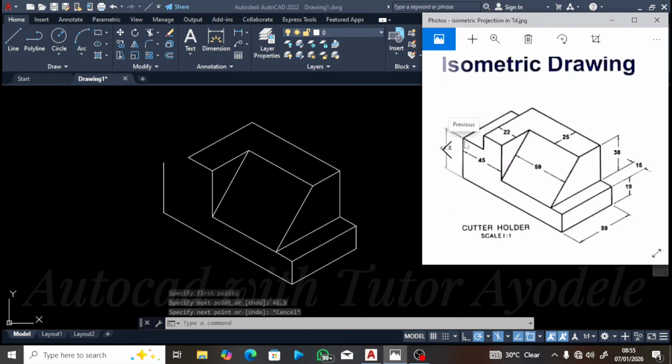So from that point, I will need to come in 30 degrees inside like this. Now we need to know the distance from here to here. If the distance from here to here is 22 and the total distance from here to here is 45, then when you subtract 22 from 45, we'll be left with 23, which means the distance from here to here is 23.